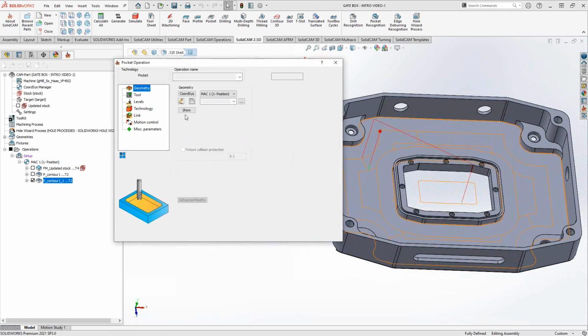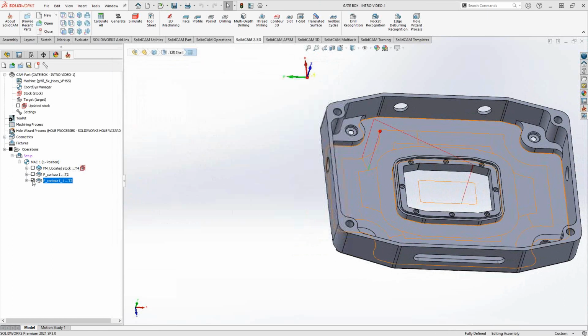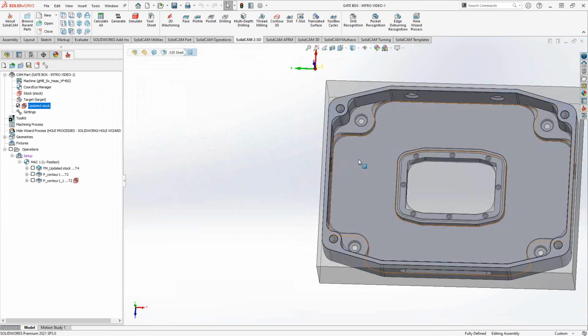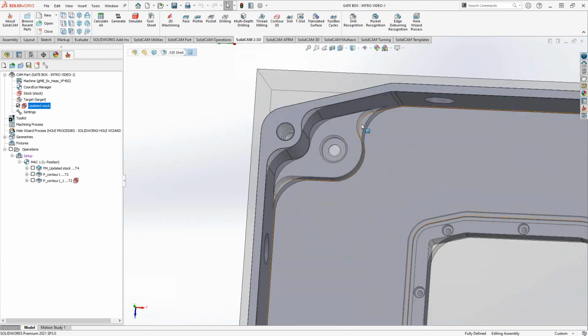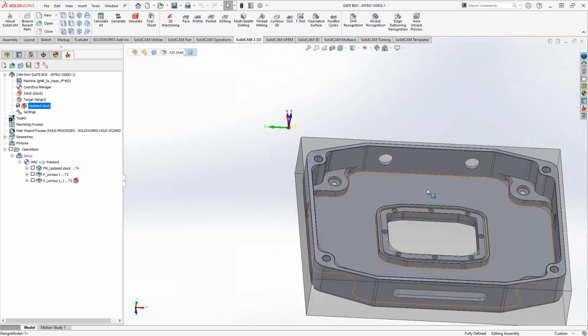So that is the rest in the Z direction. But let's say down here, if we take a look at our updated stock, I'll just check the box here and move the follower down to that toolpath there. We should see that the 1-inch tool obviously didn't do those corners. So I need to bring in a smaller diameter tool to do those corners.